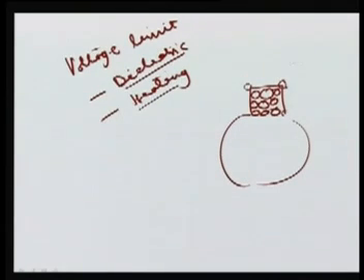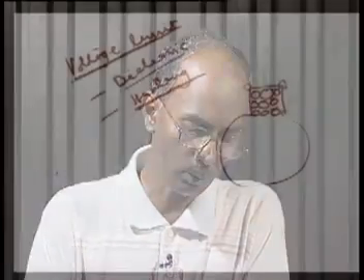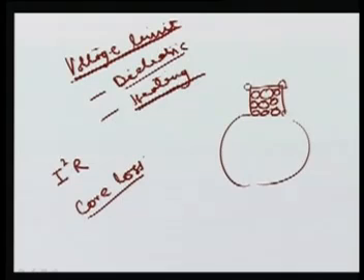So this core heating, we have two types of heating, but this voltage limit means that we cannot go for higher voltage. The heating we are discussing is due to the flux, or you can say the core heating, that is due to the core loss. We have two losses, one is the copper loss, that is the I square R loss, and another is the core loss. This core loss, we know, depends on the voltage.